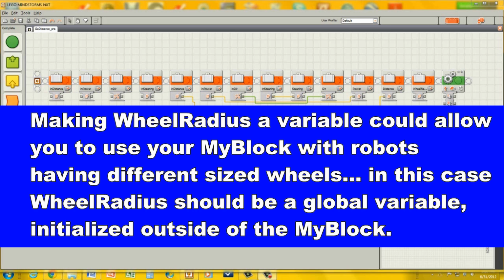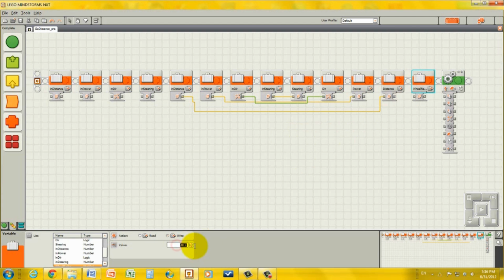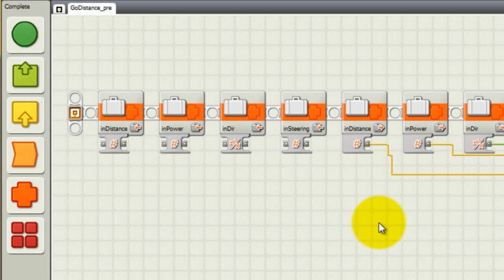After measuring your wheel radius as best you can, run the robot for a meter and then use the actual distance it traveled to help tweak your wheel radius to a more exact value. Anyways, here I'm going to write the value of the wheel radius with a value of 40.5, which is what we have found works well with the wheels we use on our robot, TubBot.